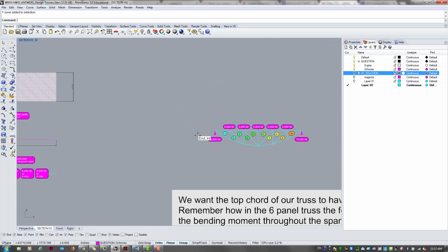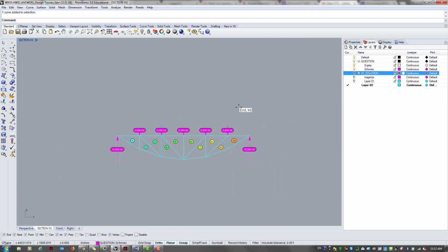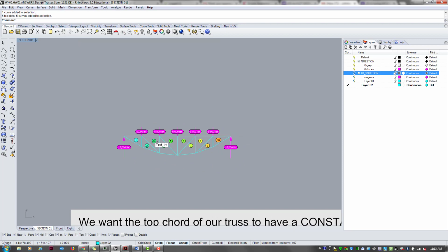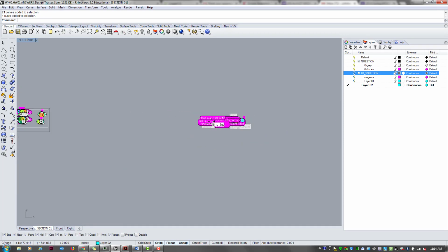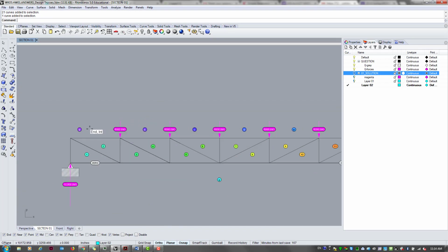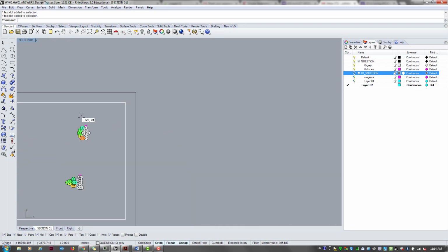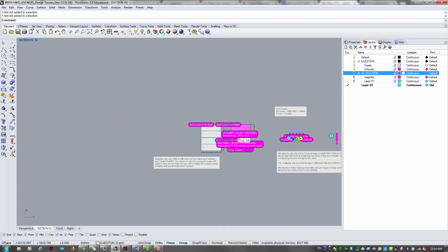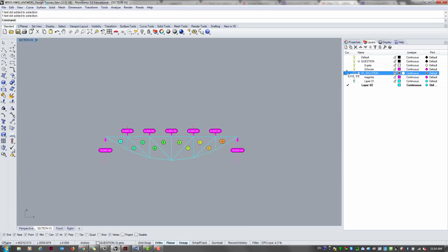So anyway, we took that step to calculate the point load, so we can translate that calculation into a diagram like this. We have a truss like this, and we have these point loads, 6,000 each and 1,500. Let me just do A, B, C, D, E, all of it. Did I have that in there? Maybe I have that in there already. So let's look at this truss, and okay, I drew them in there.